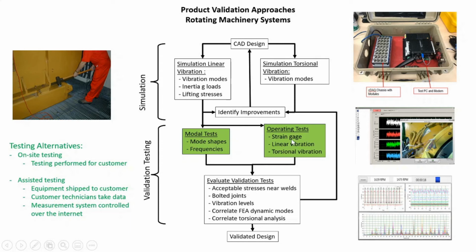Both of these types of tests are heavily influenced by the simulation results. They particularly give us good locations for strain gauges and other instrumentation, and give us an idea of what particular frequencies and operating speeds we may want to pay a lot of attention to.